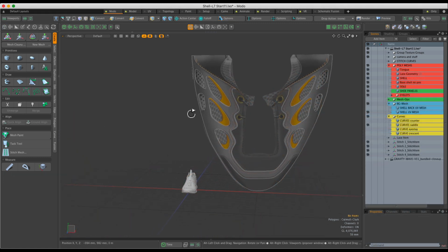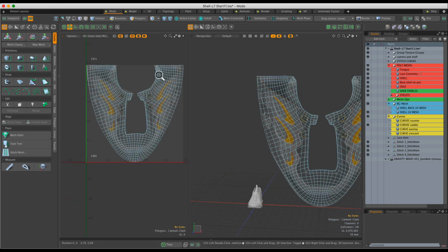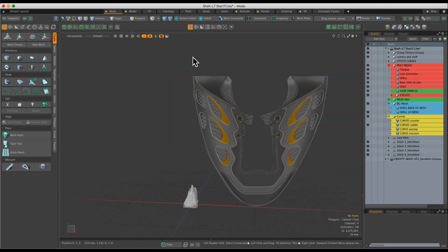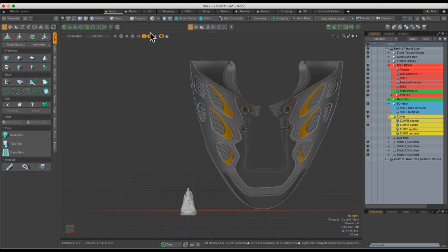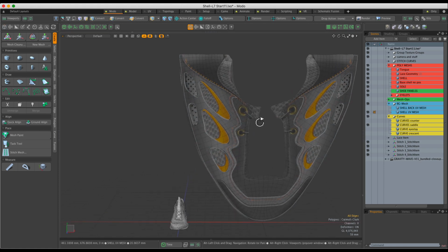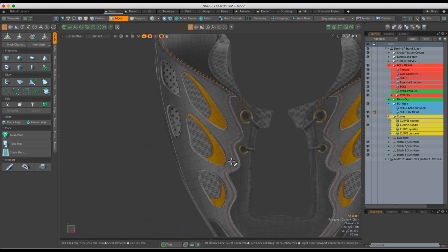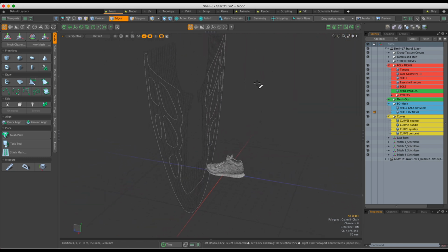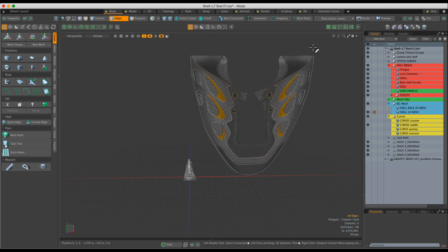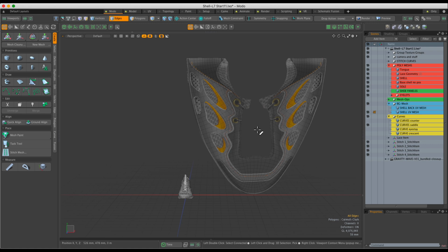If you recall, in order to utilize our UV transform, we needed to convert the UV map here to actual geometry so that we could do a couple of things. One is have a guide to draw our curves on, and the other is to have a background that the curve vertices could snap to and adhere to, so that we're creating our curve structure for the UV transform on a single plane. And that needed to be 1 meter by 1 meter square. Everything worked out for us there, and it was a bit of a setup, but it wasn't too difficult.